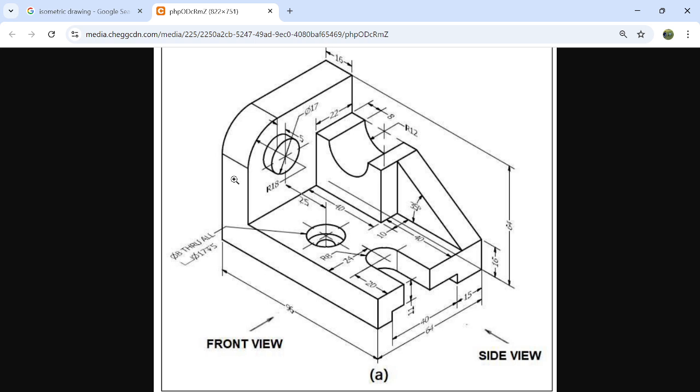Okay. So if I want to create this L shape, it has some features over here. It has a round shape and all. How to convert that in the software, we will learn that also. But we will sketch one L shape first in two-dimensional. Then we will give volume to that sketch so that it gets this particular 64 width. Okay. Then for creating this pocket, we will draw one hole, or circle, with the particular dimension given in this diagram. And similarly, we will complete it one by one by sketching different two-dimensional shapes into three-dimensional. Okay, you will understand after the completion of the object.